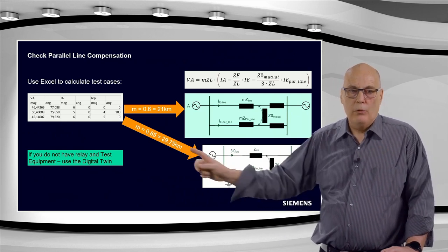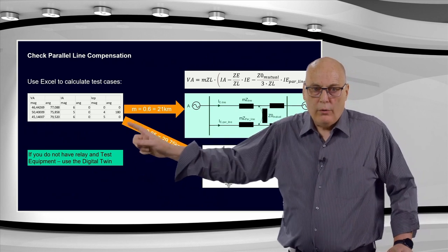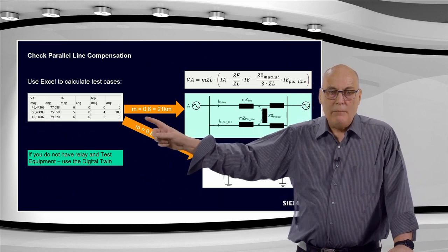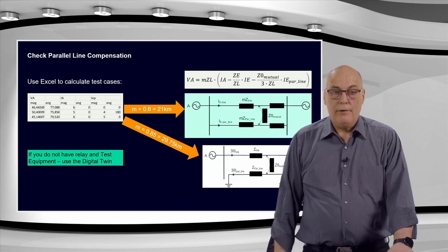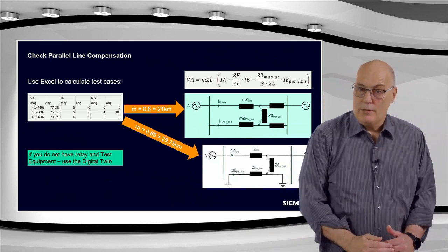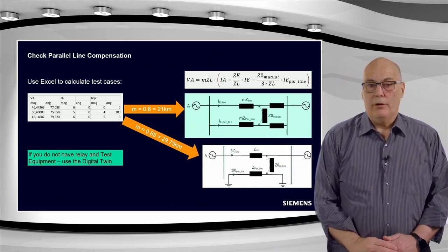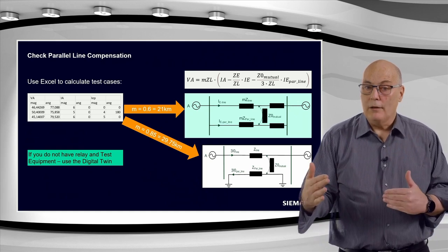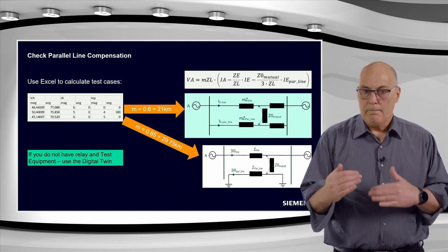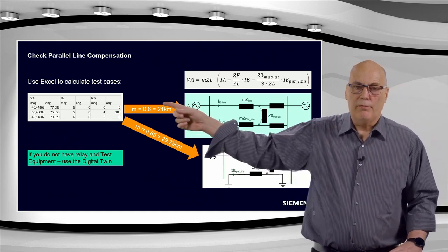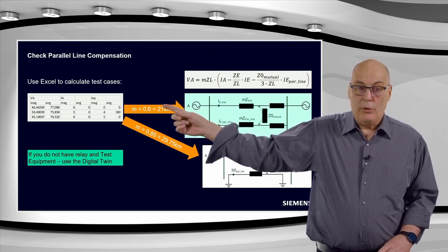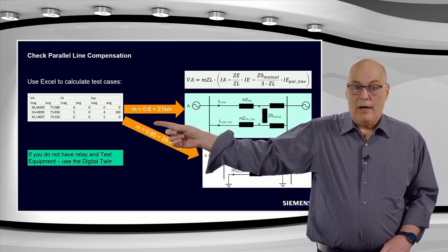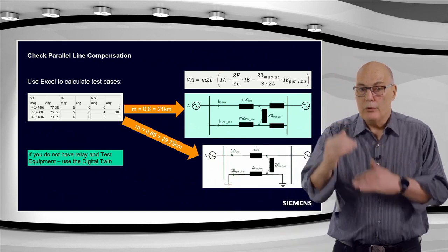And it's interesting, if you look at the voltage magnitude, although the third test has 6 amps and 5 amps in the parallel line, you can see the voltage on the complete left is only 45 volts secondary for the third test. Although it's a larger current, normally larger currents would give us larger voltages. If you compare it to the first test, which was also with 6 amps on the protected feeder, it was 46 volts. So the 5 amps on the parallel feeder actually reduced the voltage.